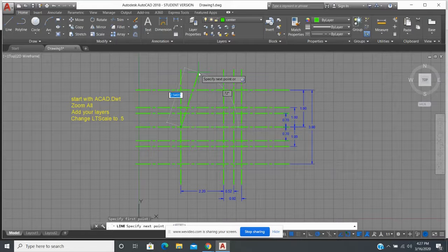So we know that there's more than one way that you can draw a line at a particular angle. You could use the method where I would type in the @ symbol, type in a length of line like 3, and then the angle symbol, which is shift comma. And then in this case, my angle would be 60 degrees because I'm coming off of the vertical, not off the horizontal. So instead, I'm going to use a little bit of the faster method here, a cheater's method.